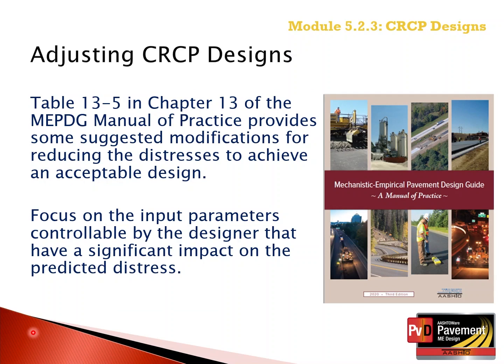Table 13.5 in Chapter 3 that we looked at in the Manual of Practice provides some suggested modifications for reducing the distress to achieve an acceptable design. It's generally recommended that the user obviously focus on the input parameters that are controllable by the designer and still have a significant impact on the predicted distress. So controllable by the designer and have a significant impact on the distress.